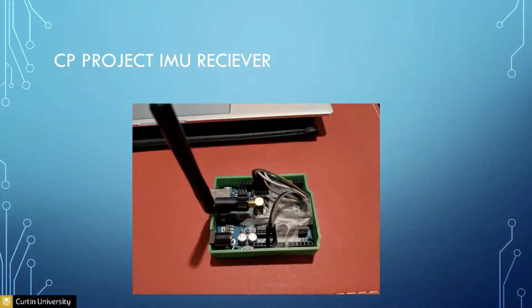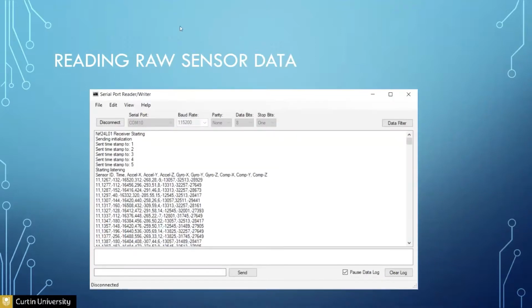Because we have a couple of people working on something similar, I'm going to show you the way that I'm capturing the information in the next slide. And these are the prototypes. As you can see, the receiver is literally sticky taped together, because it's not a product yet. I'm just working on the proof of concept and making sure the information is sent from the smaller sensors to this receiver, which is just an RF receiver connected to an Arduino, and then I use the serial port reader to read the information. And here's an example of that serial port reader.